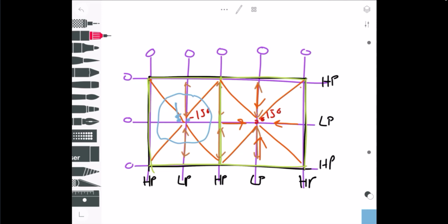But yeah, you'll very often see, if you start paying attention to buildings, look up at the parapet and you'll often see the holes in the parapet, and that's just for drainage in an emergency situation. They shouldn't be used. You shouldn't see water dumping out of them, but they're there for that emergency purpose.